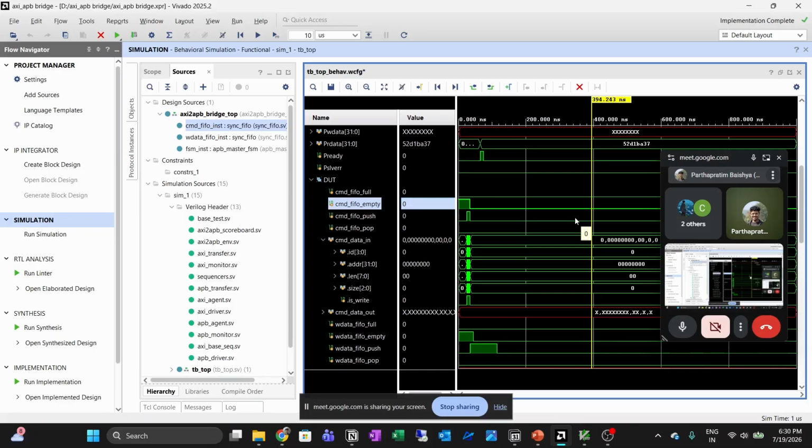Which I have to input in the code? No, see, on top of the waveform, can you see a timing 10 microsecond? Yeah. So based on that, it will simulate till whatever time you have given there. So you can increase the time there and check if it is giving you the correct data after wherever it is coming as a straight line.